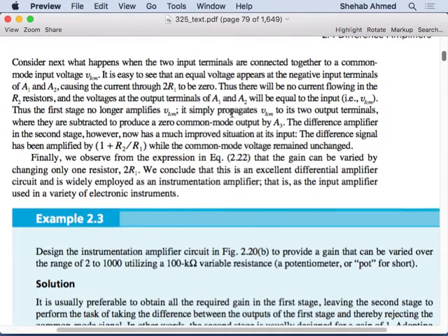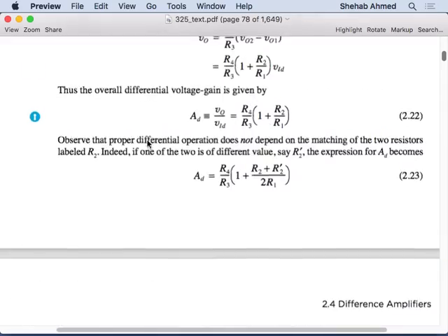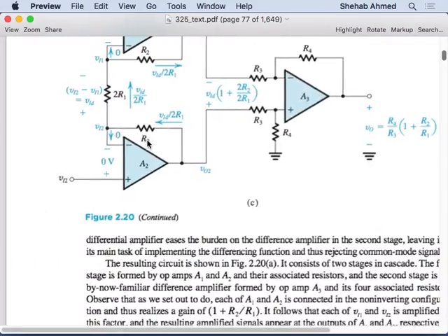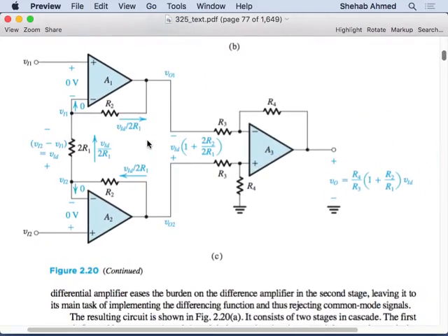We can always use the one that solved the two problems. This last instrumentation amplifier is the one we will use. I would use this one. You don't lose anything, right? You just remove a reference point. That's why selection of grounds is not haphazard. People think of how current is flowing and stuff like that before they just connect everything to ground. So this is the workhorse, I would say, of the industry.